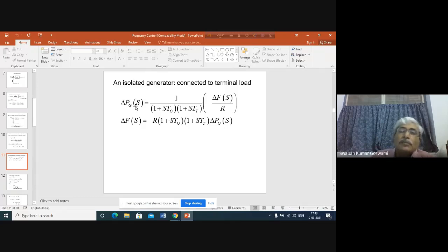So if you connect some load, how much will be the change in frequency or change in speed? If you connect some load, the generator will generate more power. How will it be generating more power? Because there will be changed steam flow rate. Why will the steam flow rate change? Because of the throttling operation of the governor. It is because of the governor operation only. The governor on its own can do this, and this operation of the governor, when the speed changer position is not moved, not changed, is called the free governor operation. That means the governor is free to operate on its own.